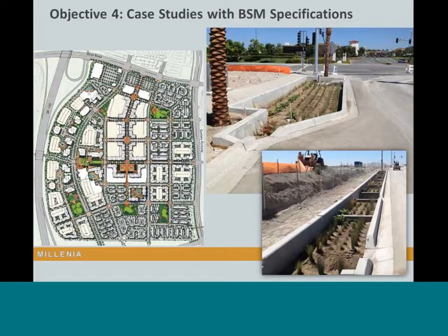Another project here, this is a streetscape project. The top right photo shows bioretention bulb outs, so I think that's becoming a little bit more popular. So you'll see the curb cuts and all of the streetscape. This is actually in what's going to ultimately be a very urban environment, very wide parkway that's all sidewalk and buildings up to the right-of-way and wide streets. So basically all of the street, all of the sidewalk are going to these bioretention bulb outs, and it helps provide traffic calming and separation of the parking lanes as well in the streetscape.